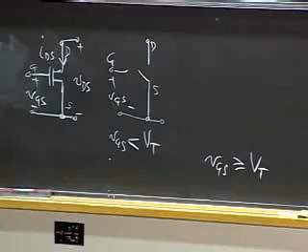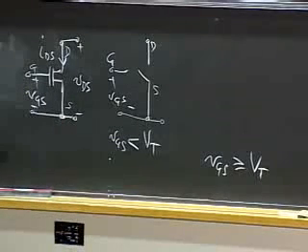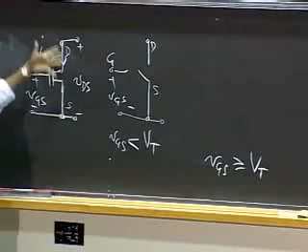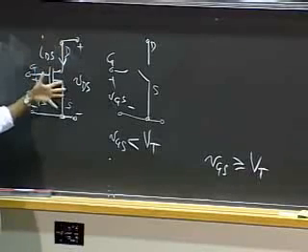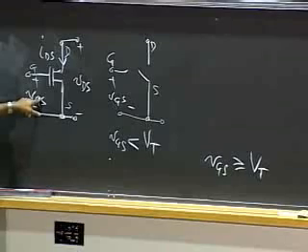Okay, we call that the SR model of the MOSFET. When VGS was greater than VT, we said that a simple way to approximate MOSFET behavior was to view this as a resistor connected between the drain and the source. That was our SR model used for the MOSFET.